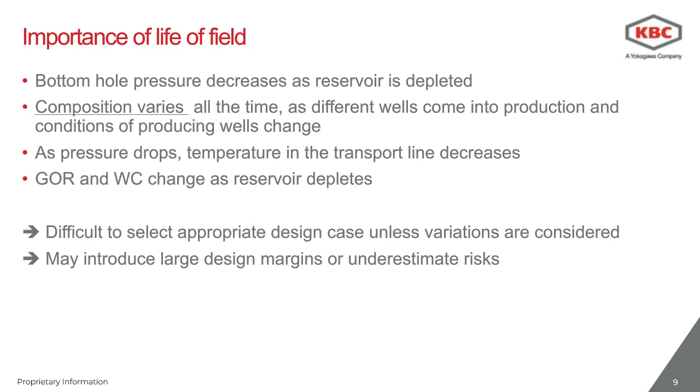Moreover, as the pressure drops, one would expect the flow rate to drop, the temperature in the transport line to drop. So potentially GOR and water cut, but also flow assurance problems may vary in terms of severity during the life of the field.